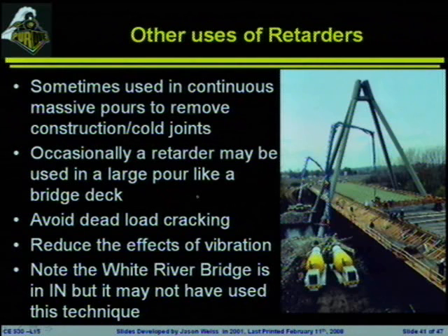As cars are going by across that bridge deck, it's setting up at different rates, and the cars are causing some vibration on the bridge and can be causing some cracking as the cars are driving by. One way that you'll see retarders being used, occasionally people will start out on one side of the job with one level of retarder, and they'll work their way across the project, reducing the amount of retarder as they work their way across, so that in theory all of the concrete would set at one particular time.